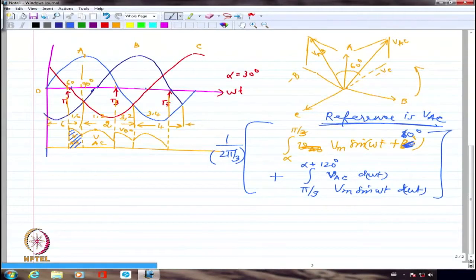So in this case, if I try to look at the supply current, maybe I have a huge inductive load, RL load, and the current is ripple free. Let me assume the current is ripple free. It is a straight current. So if I try to draw the DC current, maybe I am going to have a DC current like this. So this is the DC current.